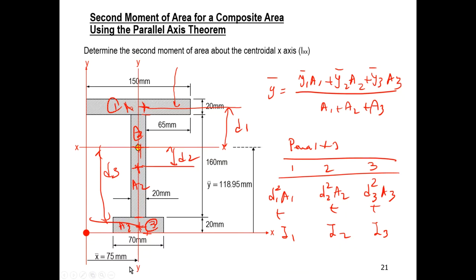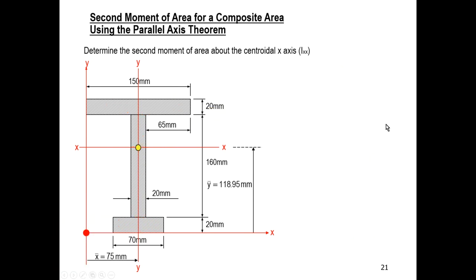All right, here we have the animated solution. So I want to find out the moment of inertia for a compound shape. First I start with a reference point. My reference point is the x-axis at the bottom. Could be somewhere else. And then before I proceed, I want to bring your attention that the way you decompose a compound shape into the primitive shapes is not unique. You can do this in different ways, right?